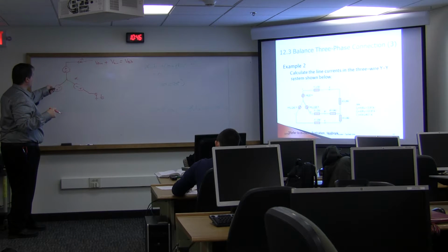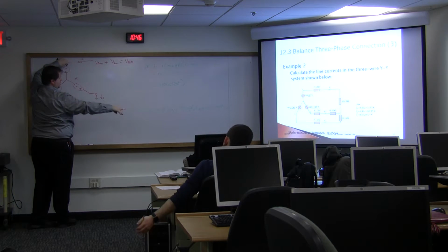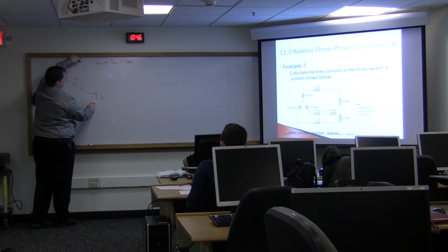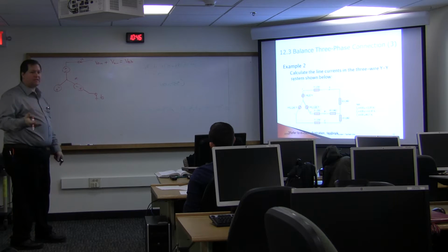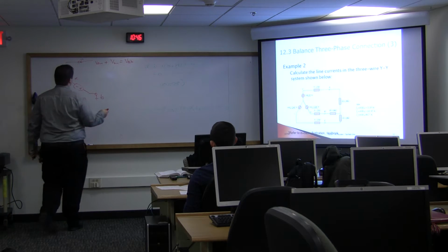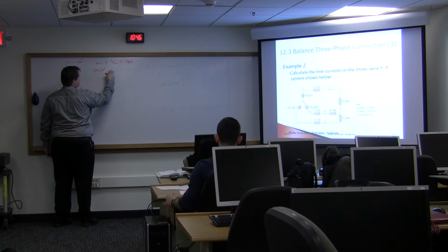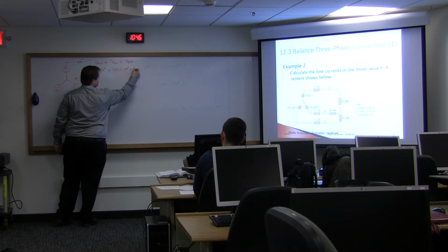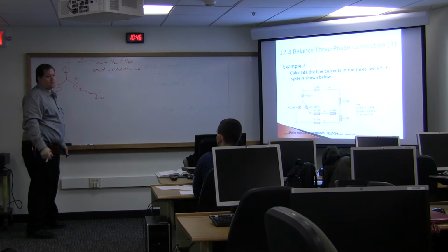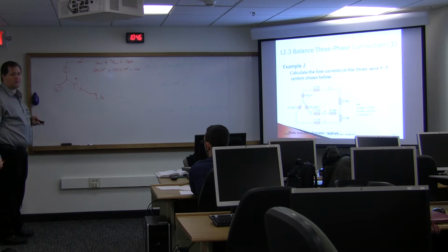Anyways, again, it's simple if you just look at this as a common point. Obviously, the voltage here has to be VBN down, and this is VBN up. So the difference between them, which is VAB, is the full separation. But they're out of phase with each other, and that's where the tricky part comes. So you would look at this as, say, this is 120 with a phase of 0, and this is 120 with a phase of 120 degrees. What is VAB? 0? No, it's not. Because I have to put each one into Cartesian coordinates, add them together, and then go back to polar form.